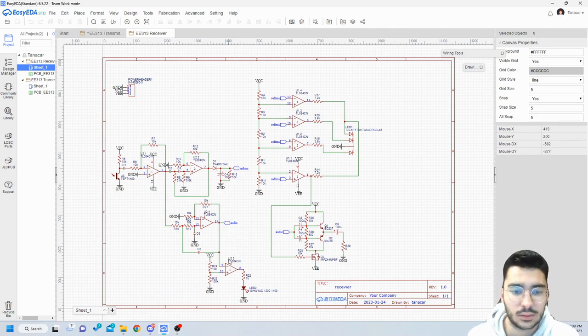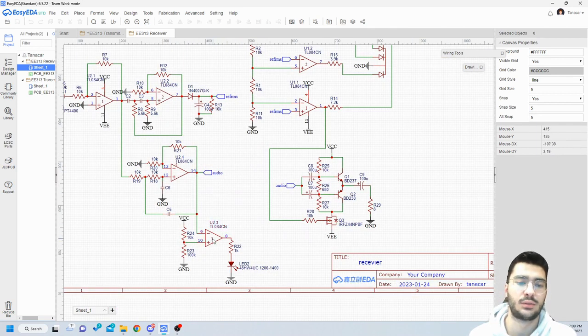And then the audio signal is compared with a comparator with a DC value of close to 14-ish volts. This is to measure that our signal is not clipping. If it's clipping, our audio signal should go in positive cycles above 14 volts. If this occurs, the LED starts to light up, but since it's flashing at higher than 10 hertz, our eyes see it as a bright LED. So that's how we detect clipping.